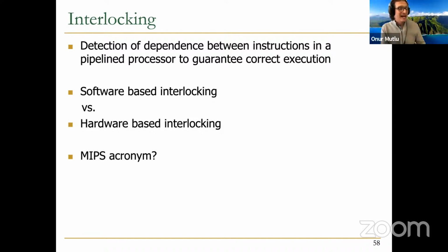And in fact, the MIPS acronym is very interesting here. MIPS is an ISA that was designed with the philosophy that hardware should be as simple as possible. It should not do data dependence detection. It should be pipelined, but the data dependence detection should not be done by the hardware. And the acronym actually stands for that. It stands for a microprocessor without interlocking pipeline stages. Meaning hardware doesn't do interlocking, software does interlocking.